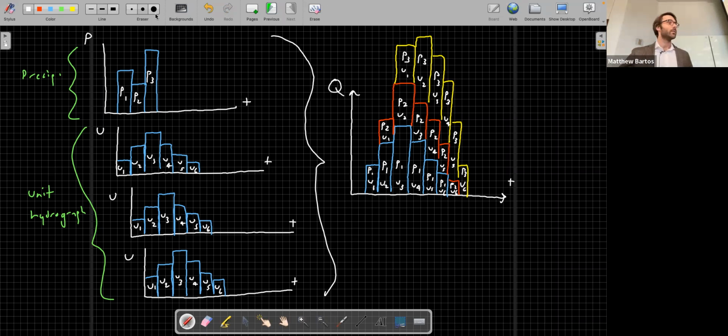Okay, so this shape here, this is the discharge response to our rainfall event P. Okay, so we have 3 discrete impulses of rainfall. Essentially, we take our unit hydrograph, we scale it by each of those impulses, and we add them together while accounting for essentially sliding over our rainfall in time for each increment, okay?